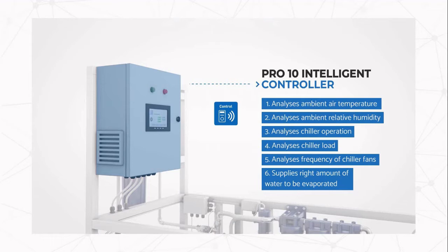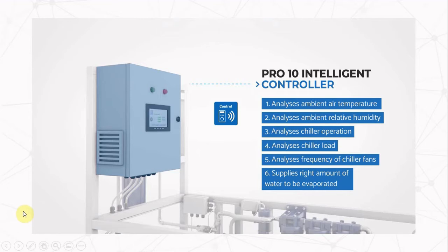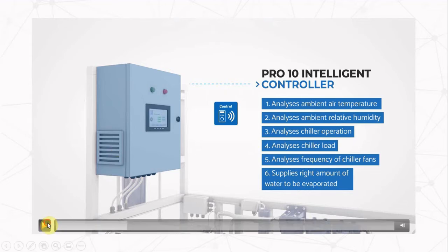Smart Cooling's operational threshold is at an 80% humidity level. When the ambient humidity reaches this level, the device automatically switches off. But why does it do that? The reason the device turns itself off is because from an 80% ambient humidity level to a 95% humidity level, the difference is not significant and the device recognizes that there is no reason to be engaged. In such high humidity levels, the maximum temperature decrease that could be achieved is just 4 degrees Celsius.